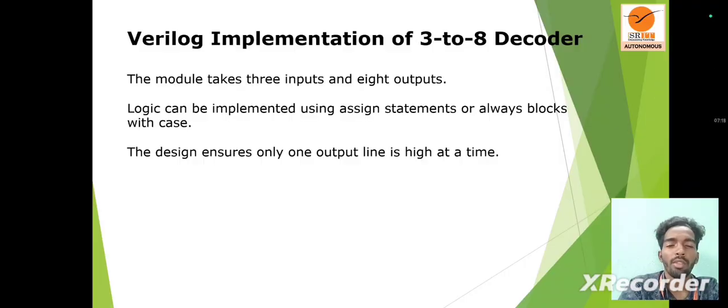The module takes 3 inputs and 8 outputs. Logic can be implemented using assign statements or always blocks with case. The design ensures only one output line is high at a time. The module is a Verilog implementation of a 3 to 8 decoder.